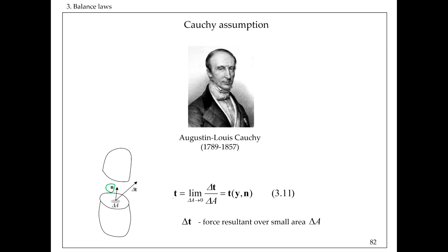In a way, this traction vector may look somewhat familiar to the definition of stress, where we took some forces and divided them by an area, but okay, we are kind of jumping ahead of ourselves. We said at one point that stress is a second order tensor, and this traction t is still just a vector, a first order tensor, so it cannot be exactly that. Also, as you can see, they are somewhat connected, and we will establish this connection, obviously.